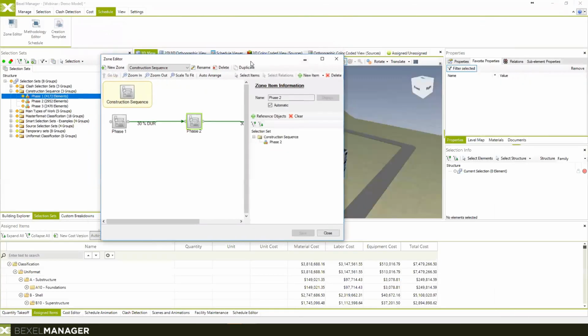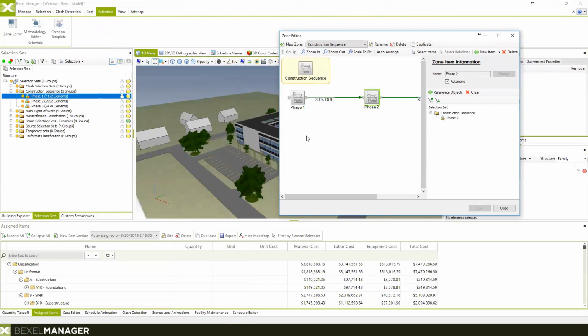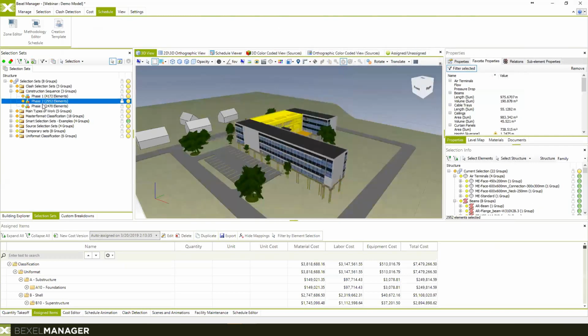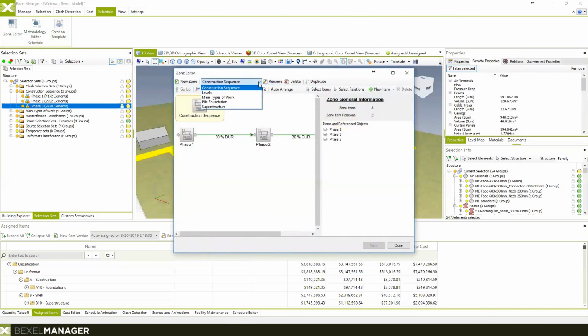And what it actually means is that we created different kinds of activities which are linked to the 3D elements. So if I select any of these activities, you see that all of them are automatically linked to our selection set. And previously I showed you these 3 selection sets, which are showing different phases or different zones of our building. In the same manner, we also created other levels of our schedule activities.